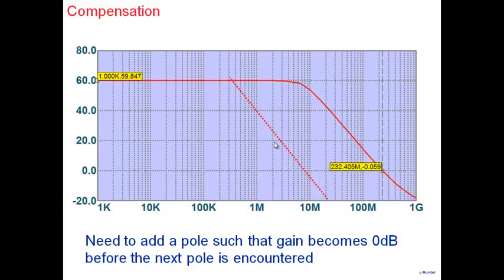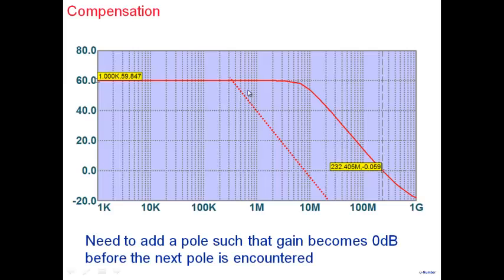Okay. So what we have to do then is, in our op-amp, introduce a dominant pole. Okay. So now how do I do that? Note that if I'm introducing a dominant pole in my op-amp somewhere here, then the frequency response can be modeled, to a first order approximation, entirely as a result of the dominant pole. The other poles are coming at higher frequencies here. So I'm going to approximate the frequency response in terms of one single pole right now. There are other poles, but they exist at higher frequency.